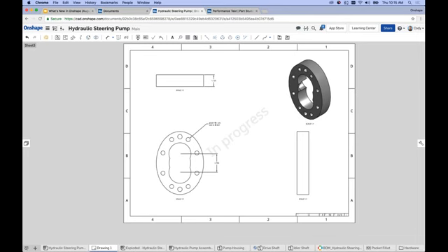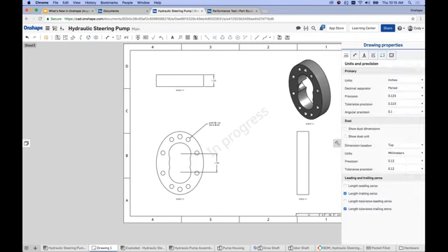The changes made to the drawing properties overwrite your template. Forgive me, I'm not sure I know what you're referring to. Changes made in the drawing properties flyout should not impact the template. This should only impact the drawing that you're currently in. If that's what you're experiencing, please let us know, but that should not be the case. So if I go through that process of export to DWT, save it as a tab, put it into a document, that should not update for every subsequent drawing that I make based off that. So if that's what you're seeing, please let us know.